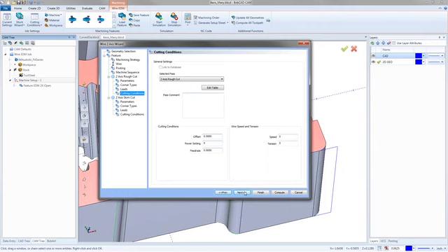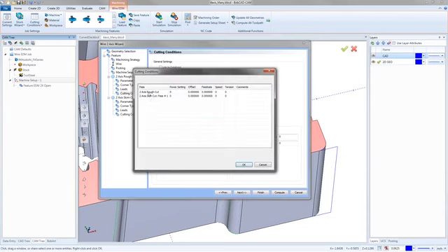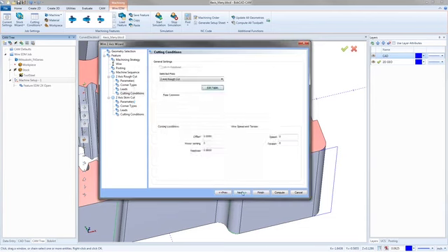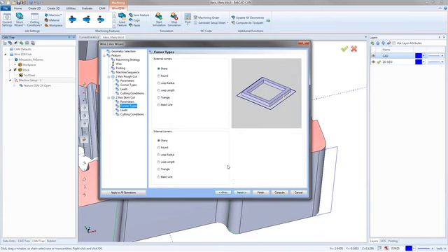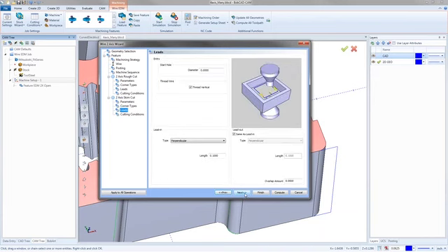You got your 2-axis. Again, don't worry about the cutting conditions until you get to the last one, because right now, if we look, there's only 2 passes happening. When I go ahead and hit next, though, I'm actually going to do 3 skim passes on this one, not tapering this time. No corner types, no leads, no changes here.